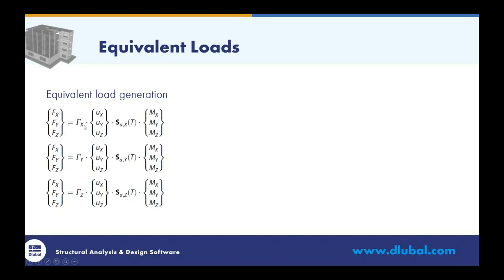Now, over on the right-hand side, we have some additional variables, such as the participation factor. We have our mode shapes available to us here. S sub A would be the acceleration from the ASCE 7 response spectra as a function of the building period. And then we have over on the right our masses. So we have all of these different mode shapes, and in our project today, we have 10 different mode shapes. So the question is, well, how do we combine all these different mode shapes for each excitation direction? And this is where we have one of two options.